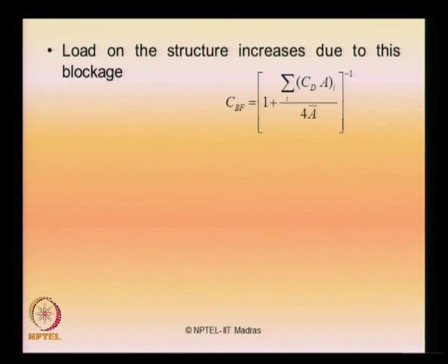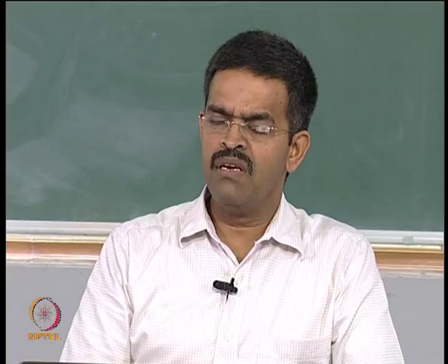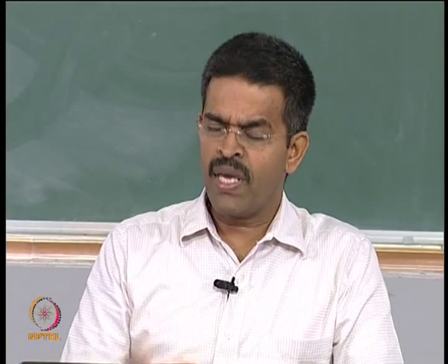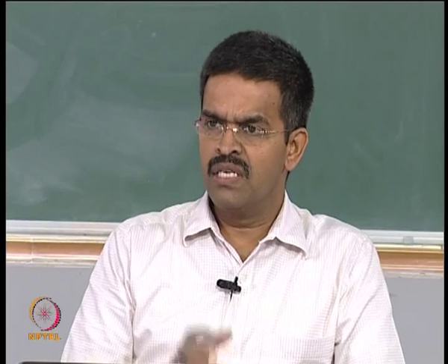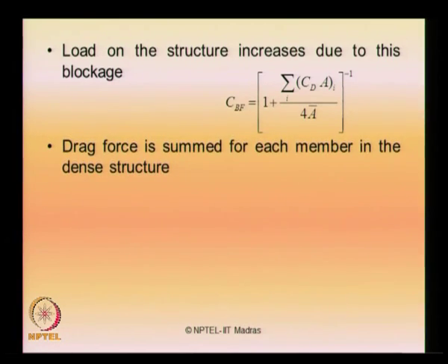It is very important that when the velocity reduces, do not be happy, because this depends on what region you are talking about, and they will induce lift forces at a different frequency which is distinctly different from that of the drag forces, which can cause complications to the structure. In fact, it increases the load on the structure. The drag force is the sum for each member in the dense structure.